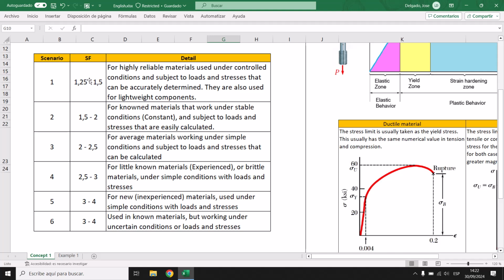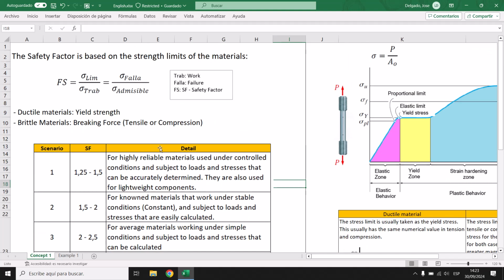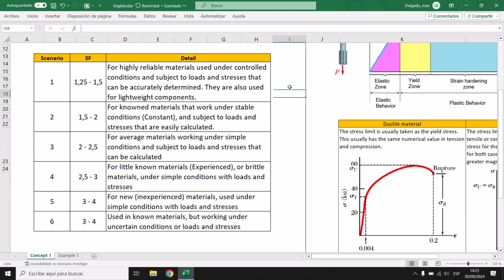Try not to use this safety factor for other cases. Don't use it. It's for shafts, or cases of strength of materials, but not, for example, the design of a horsepower, an electric motor, or something like that. Pressure vessels, something like that. No.